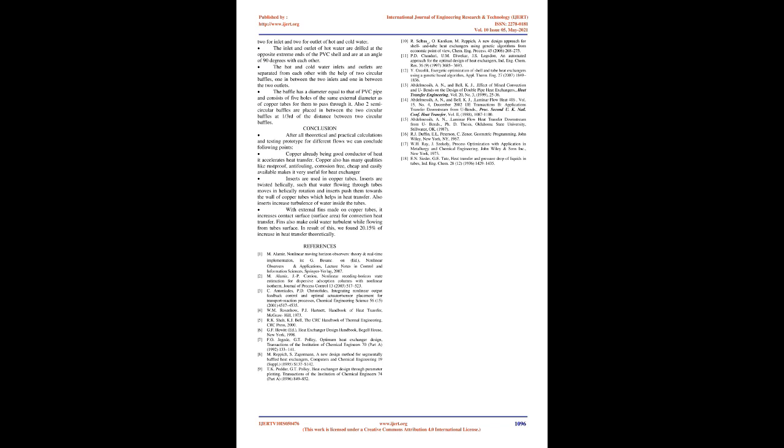Design: The heat exchanger used in this project is of shell and tube type. It consists of a shell which is made of polyvinyl chloride, PVC. The internal diameter of the PVC pipe is 110 mm. The tubes are fin type and made of copper. This heat exchanger consists of 5 copper tubes, each having an internal diameter of 12.6 mm. Copper is a very good conductor of heat, and finned copper tubes mean more dissipation of heat to the surroundings, i.e. cold water in this case. The hot water is supposed to flow through the finned copper tubes and lose its heat to the cold water in the PVC shell as it progresses through the tube.